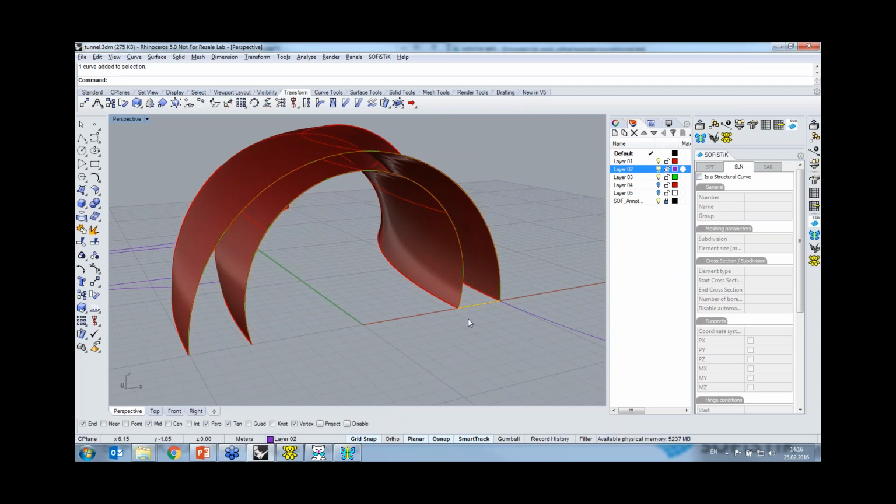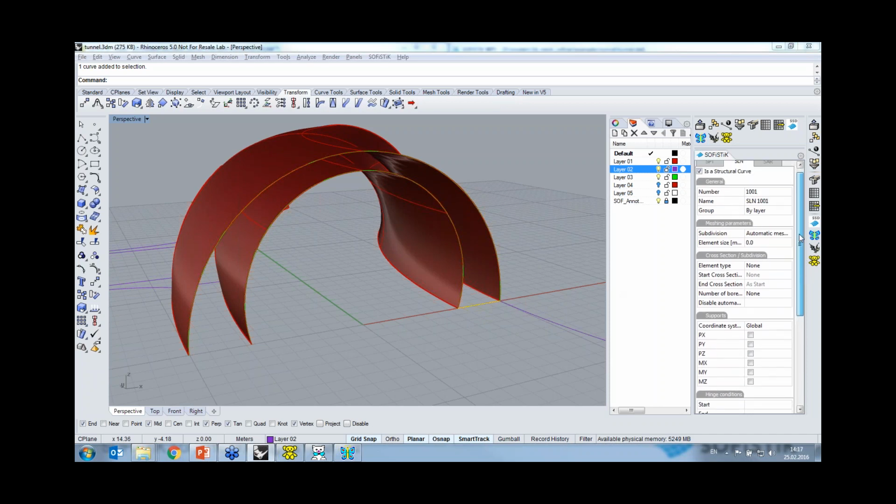Before lofting, we need to specify how many subdivisions we want to have in between these structural areas. But instead of providing this information manually in SOFiMSHA, I'm going to generate a structural line that is connected to these structural areas, and the lofting procedure will follow this line as a guiding curve, meaning that it will also follow the subdivision of this line.